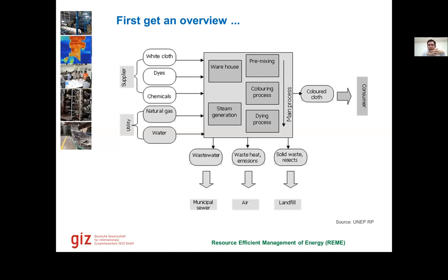If we are doing it for energy, for example, I would say we take the whole box of one company. On the left hand side, we show the different types of energy coming in. For example, electricity from the grid, coal for steam, coal for space heating or process heating, natural gas for the singeing process, for example. Or if we are purchasing steam from somewhere, we can also show purchased steam or purchased chilled water. On the right hand side, we can show our main product output. If it is a denim fabric company, for example, we can say that finished denim fabric is going out.